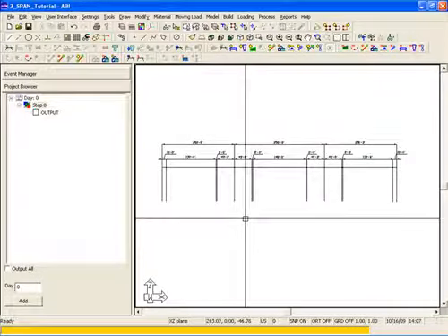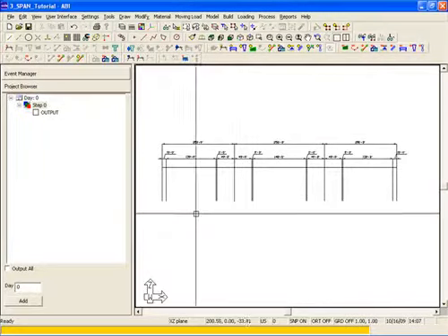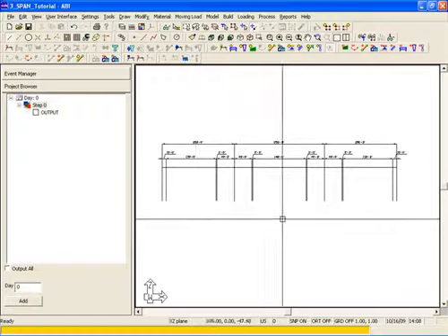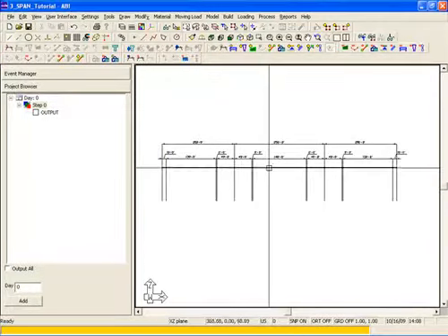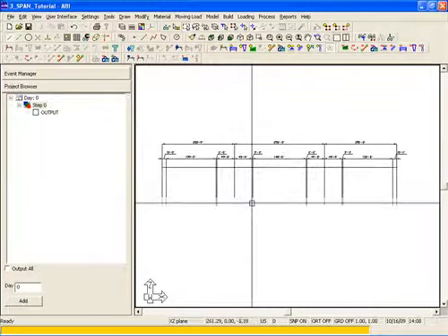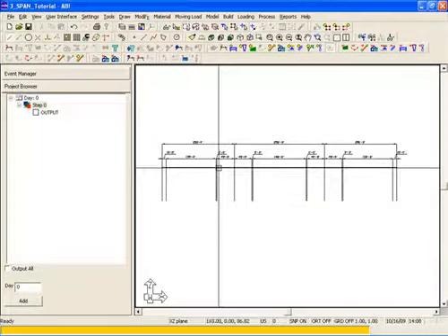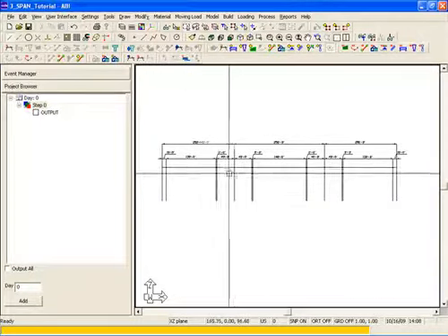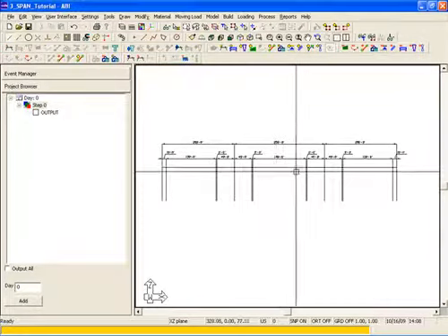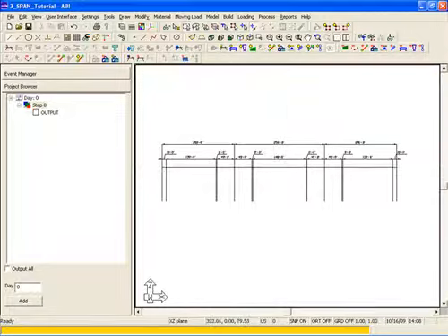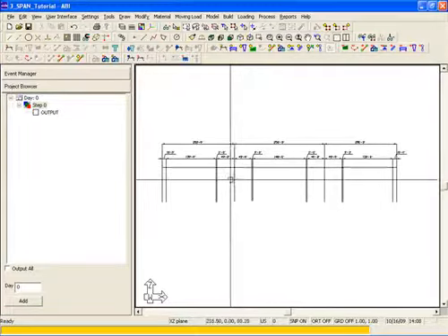Notice also that the bridge geometry is included in the drawing file that was imported. We have an end segment of 200 feet, both ends, an interior segment of 250 feet. We also show the dimensions for the closure splices, the beginning of the pier haunches, and also the intermediate spans between the closure splices for the drop-in segments. This makes it easier in creating segments along the length of the bridge.